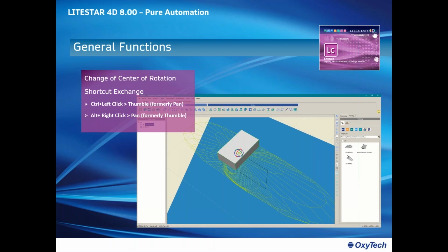But now it is possible to select a single object and the rotation will be done along the relative axis of the object. So in this case, we have the three axes, and if we select the object and press this button over here, F, focus, then all the rotation will be around this luminaire, the selected object.